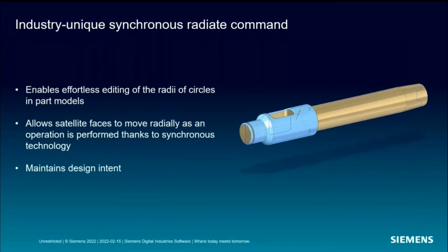Now here's another enhancement that I think you will really like. The new radiate command for mechanical design, which enables effortless editing of the radii of circles in part models. The video that we just saw, this industry unique synchronous technology capability allows satellite faces to move radially as an operation is performed while still maintaining design intent.